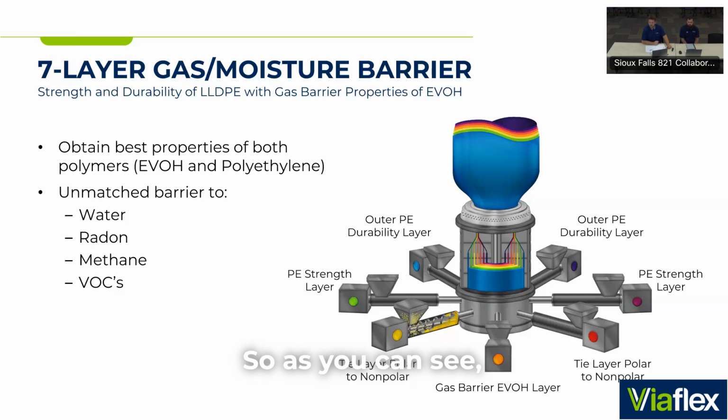As you can see, you're in the hundreds to almost 1,000 times lower permeation coefficient. So it's going to slow the material that much more than the worst case scenario of either linear low density or high density polyethylene. Pretty remarkable technology, considering it's about one third the thickness of those two membranes.